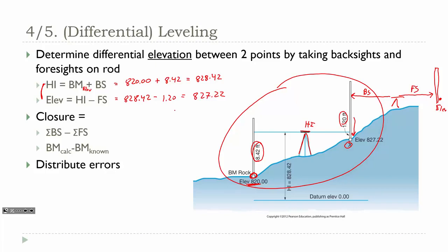Then what do you do? Or what did we do in geomatics? So the fountain was usually the point we were interested in, but did we stop when we got to the fountain? No. You came back. So we would run what was called a loop. So you go out and you come back, because if you then survey your way back, you're going to be able to calculate the elevation of your original benchmark again based on all your backsites and foresights.